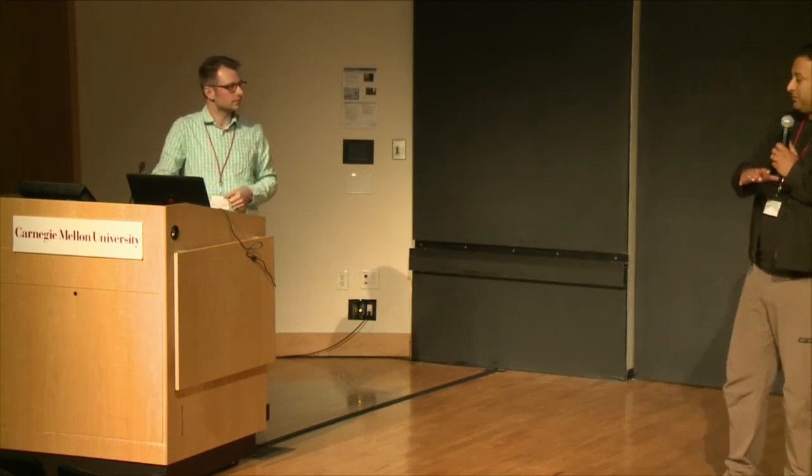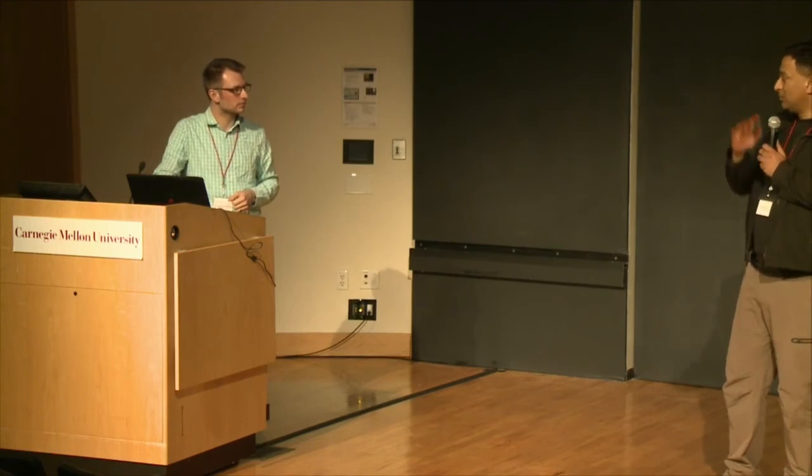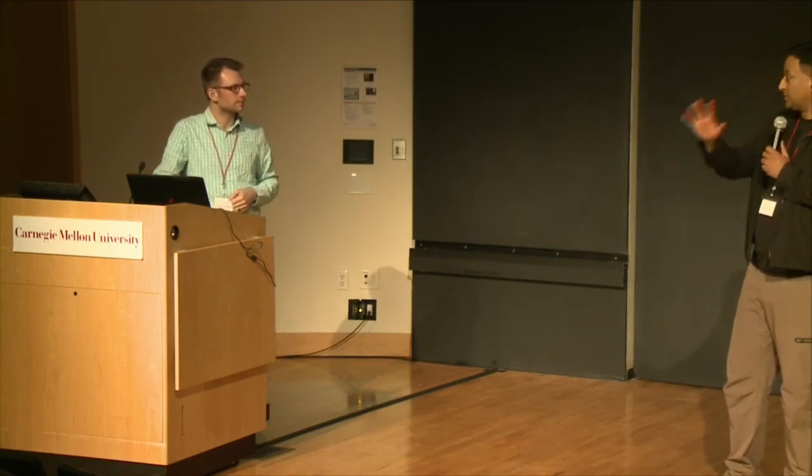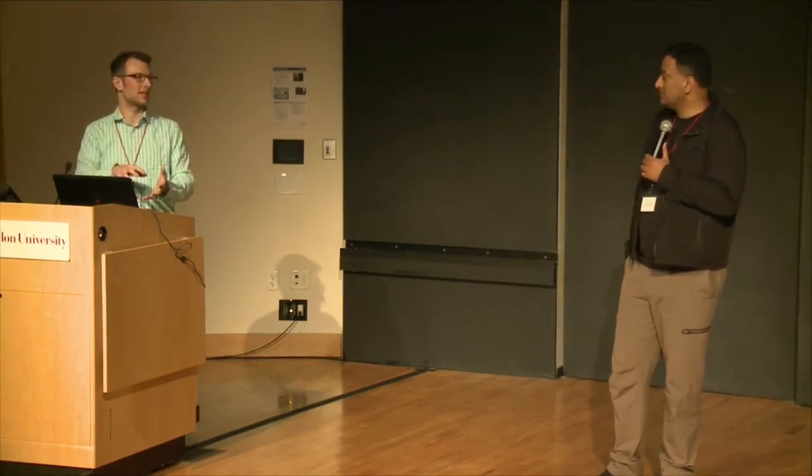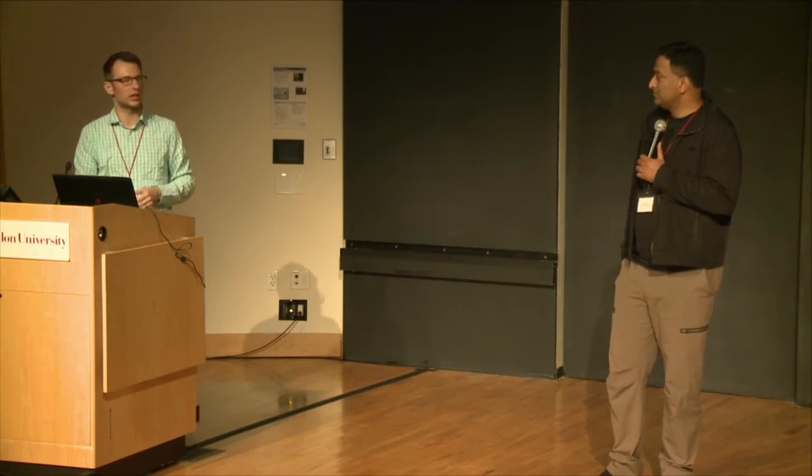So if your photons are starved in one part of the image, but you have abundant photons in the other, you think there's a way for us to deal with it? Yeah, I do think so. Some of these systems support on-chip methods where you're binning these timestamps without having to send them over a wire to a computer. It's all performed on chip, and you can achieve a higher dynamic range that way.